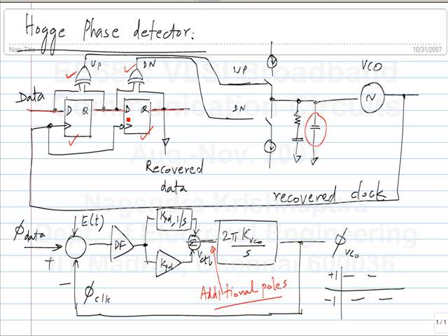So that means that essentially the VCO is not getting any correction, right? So it is as though you break the loop at this point. So the VCO will run open loop, and because the VCO frequency will not be exactly the same as the input frequency. I am not talking about VCO drift and so on here. Just because of steady state disturbances, when you apply the correction, on average the VCO frequency will be the same as data frequency. But at the moment the transitions cease to exist, it may not be exactly the same. So after a while the phase of the VCO will drift away from the correct one that is required. Okay. So in any CDR there is a limit on the number of consecutive identical digits that can be tolerated.